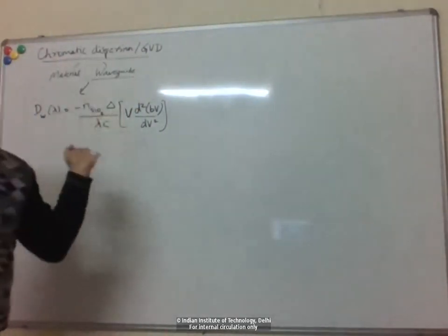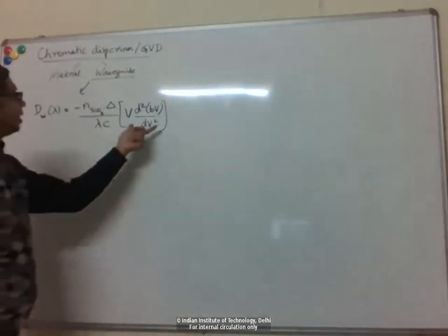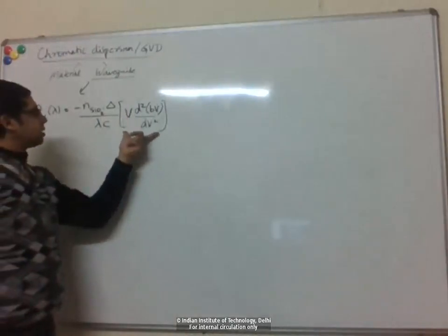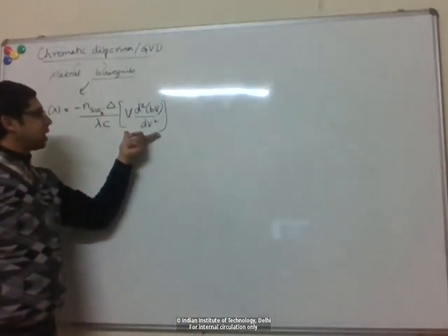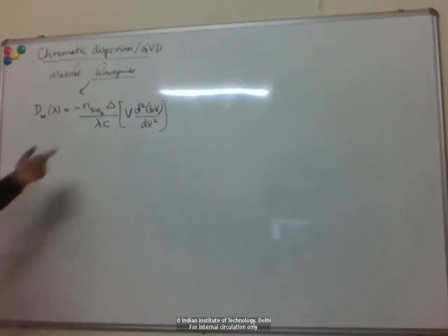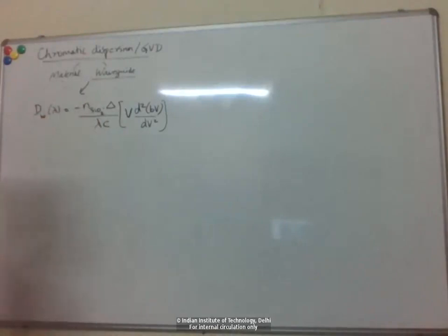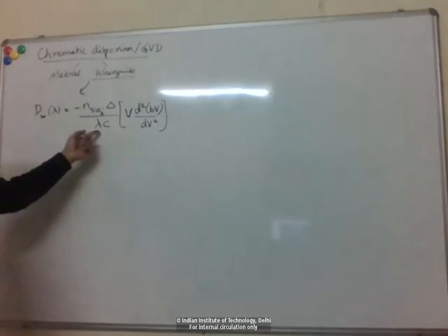So these bV curves are universal for a particular type of waveguide, right? So for a step index fiber, we have these universal bV curves, right? So we can basically compute this factor here for any step index fiber, right? And then we can easily compute the waveguide dispersion just from these parameters. This is also, we know, right, for glass, what is the refractive index.